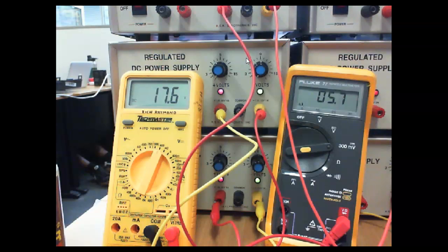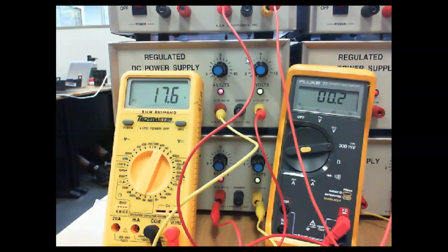So this is free spray, by the way. If you get this stuff, don't spray it on you because it'll give you frostbite. We use this a lot to try to troubleshoot. Sometimes in electronics, things get hot, and when you cool them down, they work right. And we do that sometimes to find bad parts. So I'm going to come up here and spray it. And you see the leakage current did what? It did a nosedive. So that means this leakage current is controlled by temperature. We've always got it. But if temperature goes up, leakage current goes up. If temperature goes down, leakage current goes down.